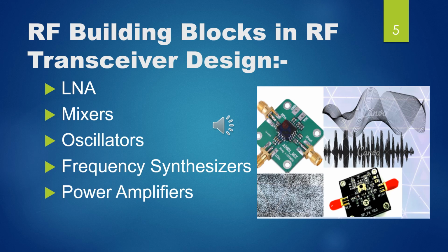Oscillators are also a very essential component in any radio frequency system. It serves as a signal generator in a transmitter. In a receiver, the local oscillator is used together with a mixer to convert the received RF signal to an intermediate frequency signal. These oscillators can also be modulated by low frequency analog or digital signals.